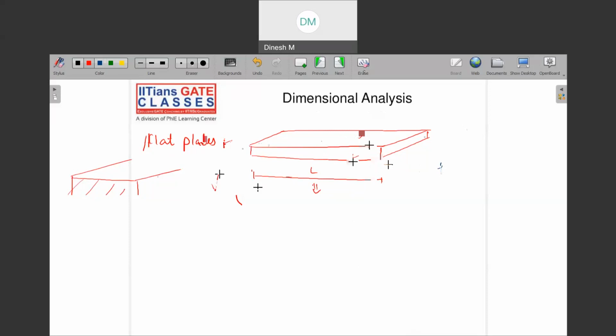So now can I write down that this HD upon K is a function of Vd into rho upon mu, and second thing, Cp upon K. So now I can see that I have formed a group of numbers, and I can see how my H is dependent upon the flow properties. Got the idea? So this is one case.